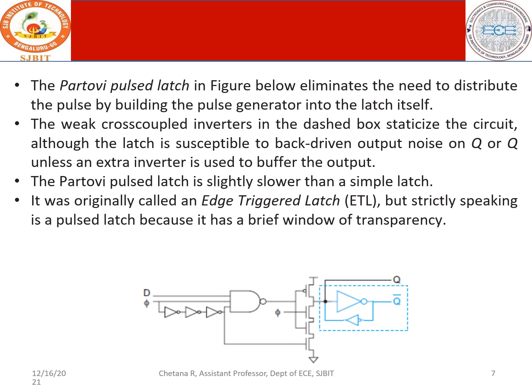The Partovi pulse latch is slightly slower than the simple latch. Of course there are many extended features, but it is still considerably slower than the simple latch. Therefore earlier this was called an edge-triggered latch, ETL. But strictly speaking it is a pulse latch because it has a brief window of transparency. So the Partovi latch is meant for all these applications. It has a better way